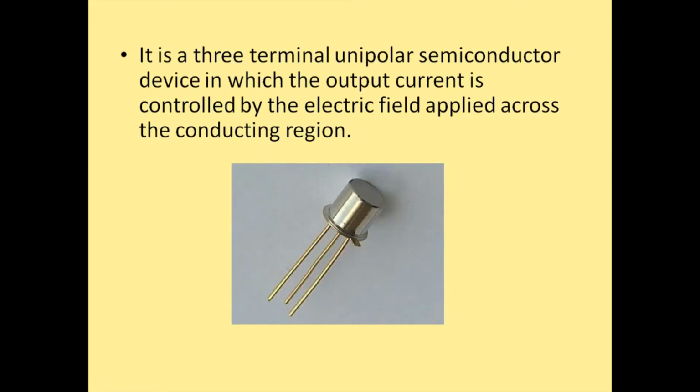Now let's know a little bit more in detail about this particular component. Of course, we all know that most of all these components, whatever we study, they are usually made up of semiconductor material. Similarly, this particular FET is also a component that is made up of semiconductor. Now, the last year component, that is the BJT, in that the alphabet B stands for bipolar. Bipolar means it was a hint given through the name that the current conduction in this particular component happens because of both the polarities, that is both the positively charged holes and the negatively charged electrons. That means both the polarities are responsible for current conduction.